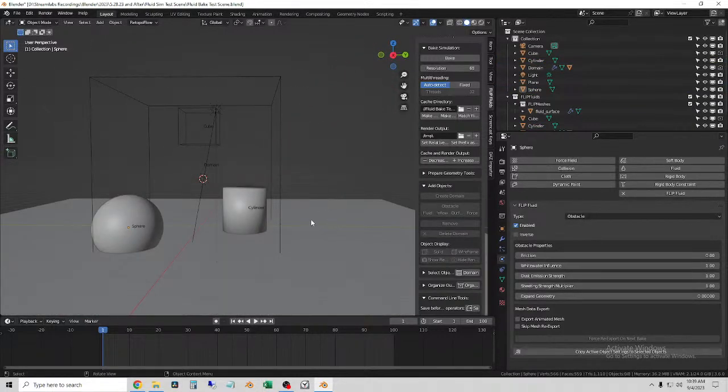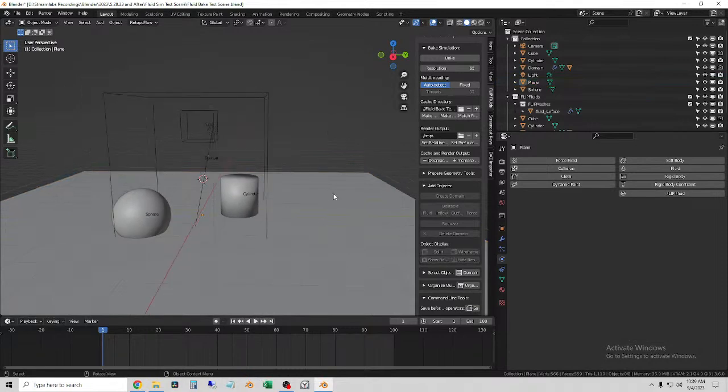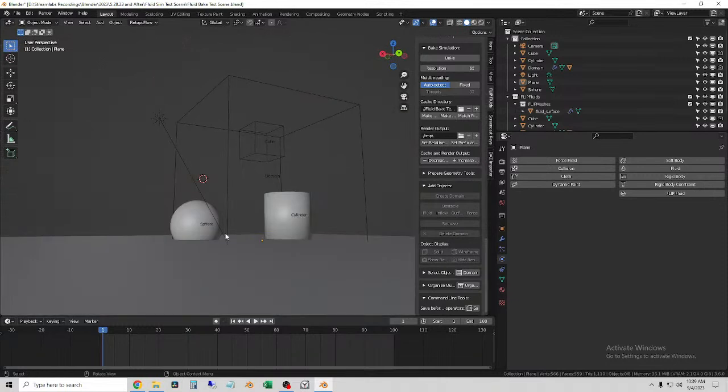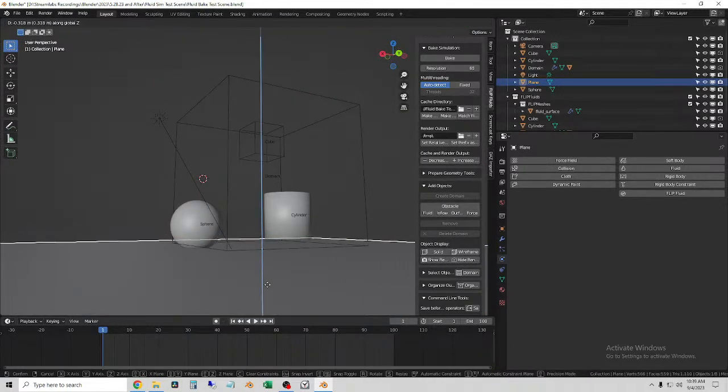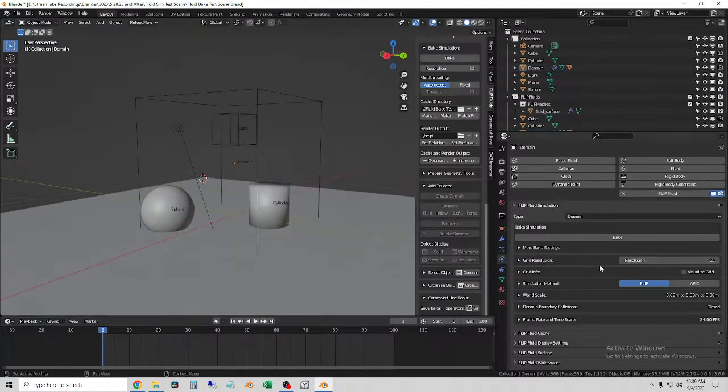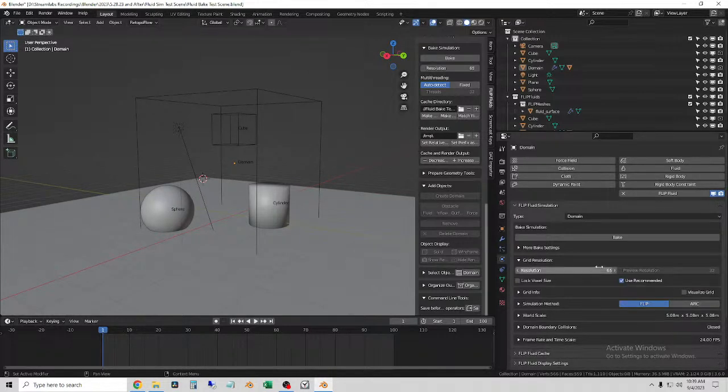Okay, so now this floor actually isn't really doing much. I think it's actually just going to go to the bottom of the domain. So I think I'll just kind of move it to make it look okay. All right. So grid resolution: number of grid voxels on the longest side of the domain. So if it's a perfect cube, the resolution should be number of divisions in each direction. So that should actually line up okay.